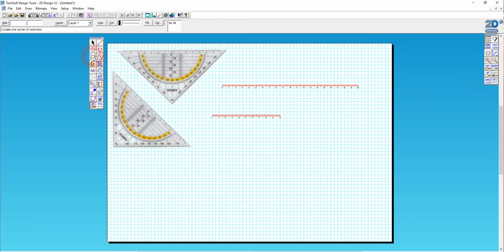So to do that, let's just come to a square tool here. I'm always working with grid lock at the moment, so everything snaps beautifully, makes my life so super easy. If I imagine that I want to have this as a square, then obviously I could just do a square here. Looking down here at the relative grid references where my mouse is currently hovering, when I go back onto the drawing area, you can see I want to take that to 100mm in the relative X value, and in this case it's minus 100 in the relative Y, because the origin is the bottom left of my drawing area.